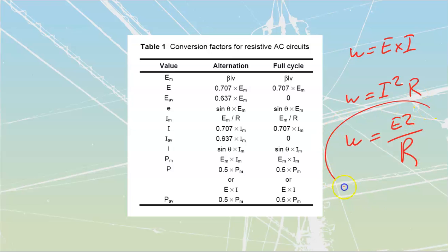We're going to use this formula actually a fair bit, the voltage squared over top of the resistance, which gives the power, because most of our electrical circuits are connected in parallel, which means that all of our values are always going to see the same value of voltage over top of them. It makes it a really handy one for us to use. So expect to see that one a fair bit, get familiar with it. And for the rest, it's just going to be straight Ohm's law that we're doing through a lot of the rest of these as well.